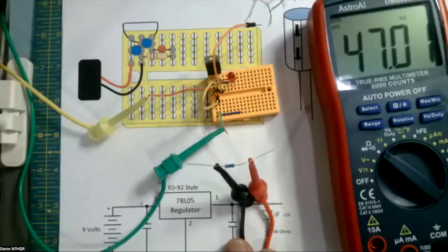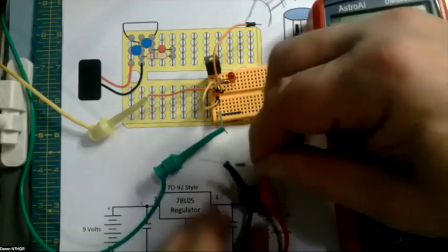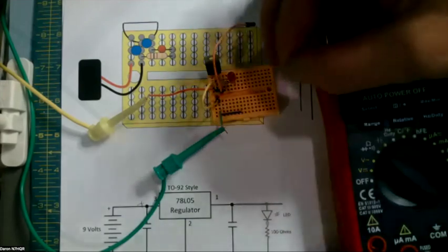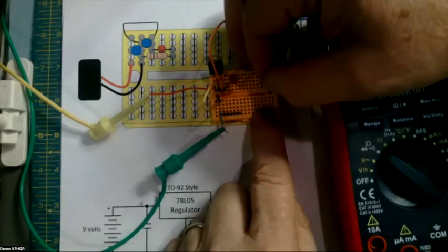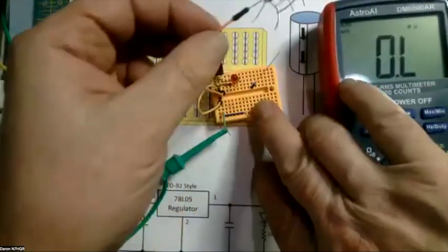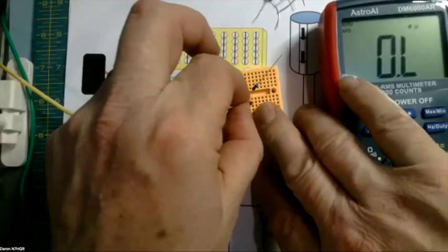We want to use this to charge our capacitor. You've got a 5-volt supply, right? Correct. You'll need to put the resistor and the capacitor in series. Of course, that's an electrolytic, so you'll need to make sure you have the polarity correct. So what we're going to do is take our 5 volts.